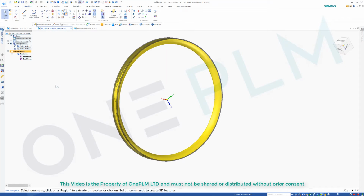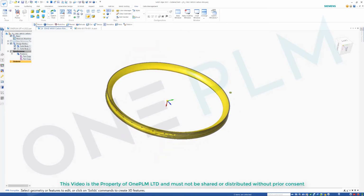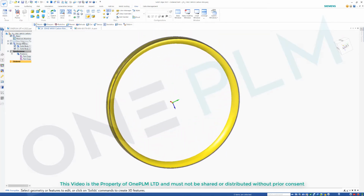So the first thing we're going to do, if we've got our bar on here, is go to ordered modelling. If we haven't, we right click and go transition to ordered, and that's going to take us into our ordered modelling option. To make sure that we've got a less complex face to apply our graphics to, we're going to split the face on there.